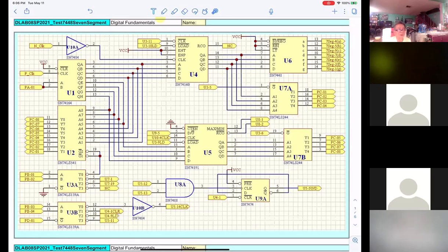Okay, gotcha. So if you want to enable U7B, then you just call enable U7B. It will set pin 19 to 0. That means it will write to port B, pin 1, pin 2, to make sure pin 6 is 0. Does the thing I put into the function make sense to you?